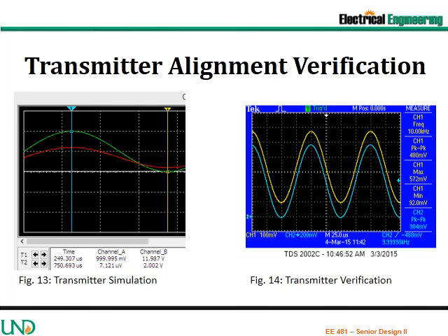The alignment verification of the laser diode allows the user to be assured that the laser can be handled safely as described in the laser safety section. Additionally, when transmitting analog baseband signals, this ensures the linearity between the commanded strength and the emitter power.